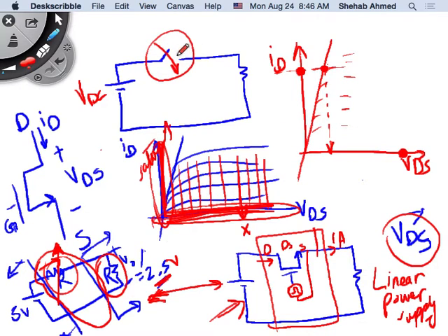For the ideal switch, when it's on, I have current flowing through. If it's a pure ideal switch, then you have current going through and there's 0 voltage across it, right? But think of this ideal switch as something that has a small resistance as well. If it has a fixed small resistance, then the power drop across it, when there's current flowing through, is a small value.